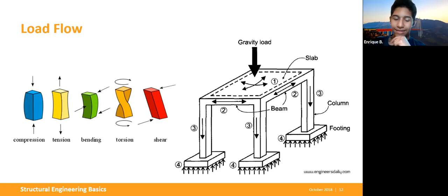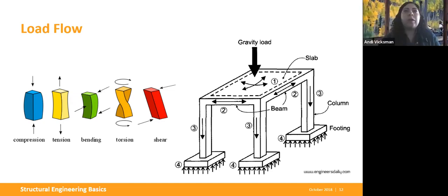No, I also had the factors of the wind or the ground shifting, like maybe if you're in California on that line. Yep. So you got even further. The loads that we've been talking about so far, like dead load and live load, are all what we call gravity loads or vertical loads, because those all act down on your structure, right? People are acting as a load down on your structure. If you've ever taken physics or drawn a free body diagram, that's like our downward loads.